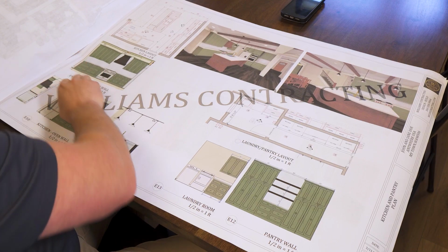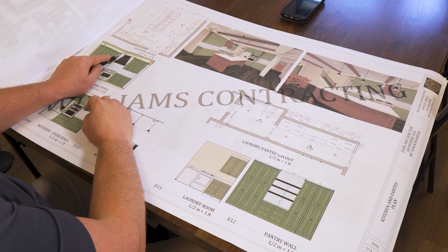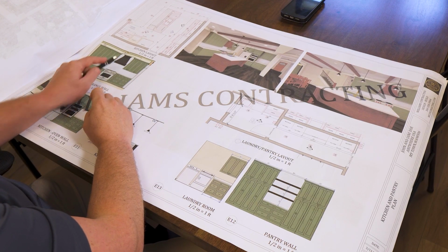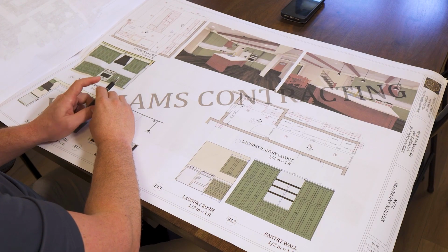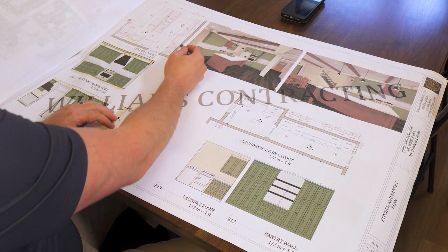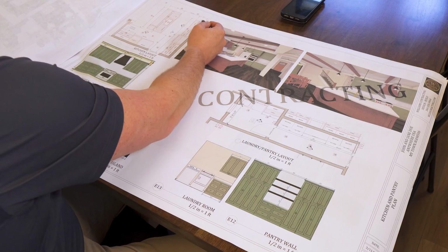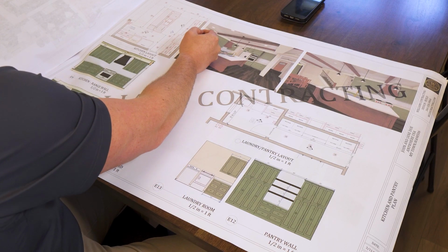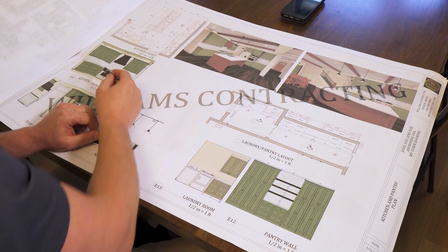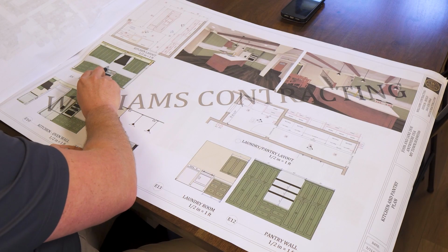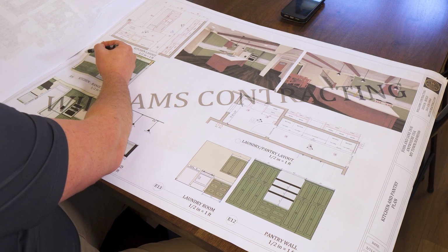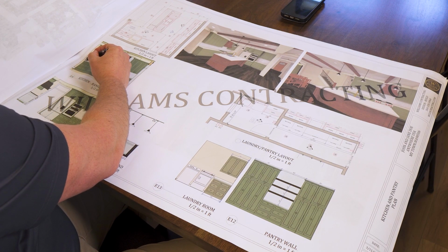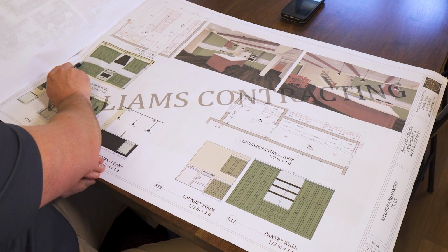Inside of here, we have an elevation. It shows a critical dimension of 42 inches between these two cabinets to make sure the space is there for the hood, and everything else is laid out really nicely. Once again, the dimensions for overall cabinet size are on this sheet inside of the cabinet labels, and this sheet gives you a good clean reference. It also shows the location of the backsplash being all the way up and around the hood, so you know where everything goes. The end of the backsplash ends with the cabinetry here, and ends with the countertop at the end.